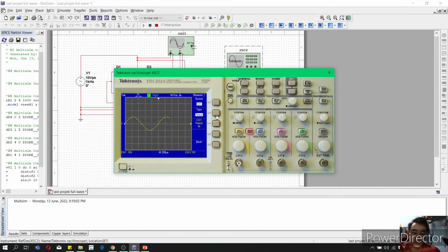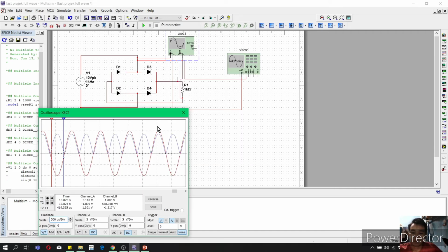So we can conclude that using any oscilloscope, we can get the same value. For the output signal, to measure the amplitude, we can use the blue color waveform. So the amplitude for the output signal, channel B, is 8.5 volt, and the period is 508.065 microsecond.